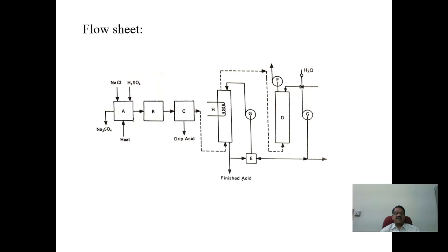Here the hydrochloric acid is scrubbed with coke to separate the other entrained particles, and then the acid, hydrochloric acid, is fed to cooling coils which are provided in the absorber there. After cooling, the product is taken to an absorption tower where water is used.